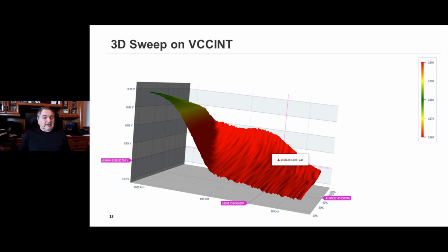And it's not flat. Like in an ideal world, it would be flat. Or would it? Because with these high current devices, we have load line, okay? And load line has been designed to help us meet regulation. So as the current output goes up, the target voltage goes down.